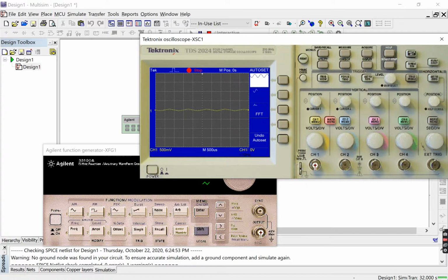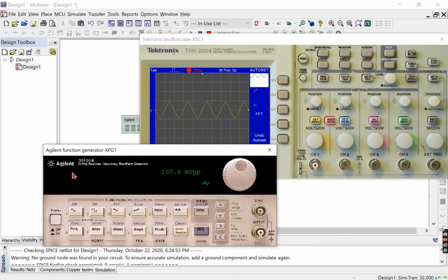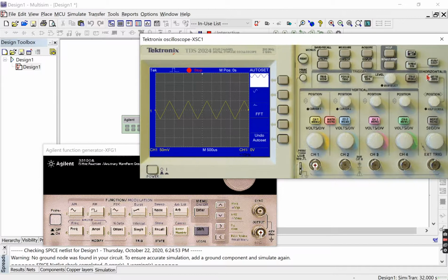You can also use the arrows from the keyboard. It's a bit easier if you do that. So control the knobs through the arrow buttons on your keyboard. Currently we're generating a rectangle signal of 100 millivolts peak to peak. Let's go back to the sinusoidal signal. Notice that the oscilloscope is currently stopped because we pressed the run/stop button. So let me press it again. This way we'll see the signal simultaneously.